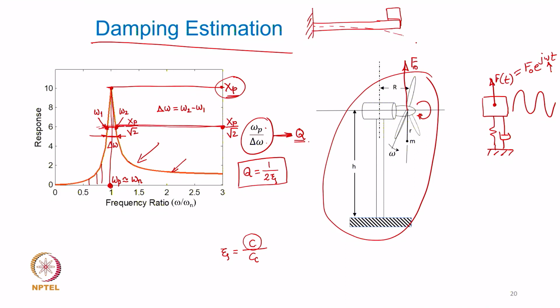So, I basically give a gentle small tap, or displace it and then release it. Once I displace and release it, it means that I am giving some initial excitation to the system. Then there would be a time displacement plot that I will get. This is the amplitude and this is time. This graph, you remember, we have discussed for an underdamped case, the amplitude logarithmically decreases, and we defined a parameter called logarithmic decrement. It was shown to be 2 pi zeta over square root of 1 minus zeta square.